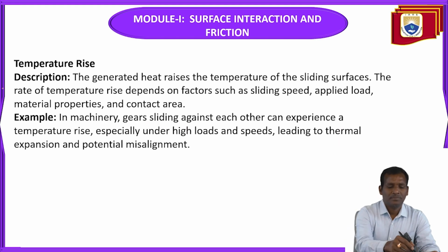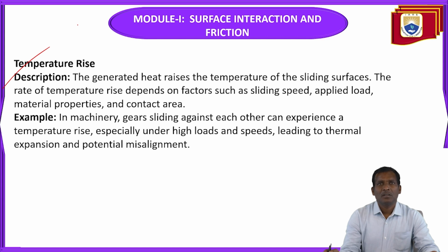Temperature rise. The generated heat raises the temperature of the sliding surfaces. The rate of temperature rise depends on factors such as sliding speed, applied load, material properties, and contact area.